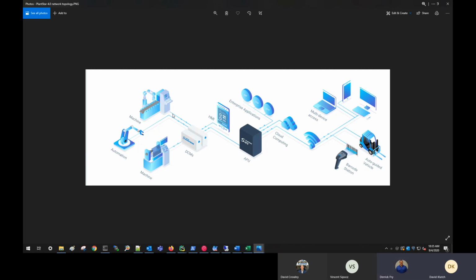Okay, it brought up a lot of good points too, because I'm talking about these machines on the factory floor and the DCMs here. Like we said, you can have 16 machines connected to one DCM. If you have more than 16 machines, then you'll just get another DCM, so there could be multiple of these physical DCM boxes on the factory floor. Those are communicating back and forth. This DCM is collecting that data from the machines. I'll get to the APU in a second, but it's forwarding that information to a central APU unit,